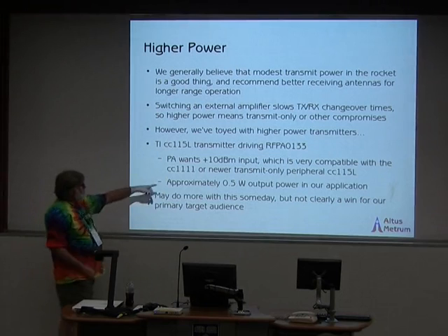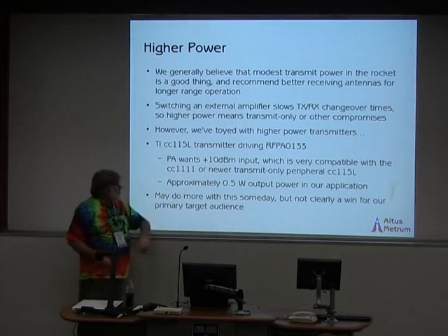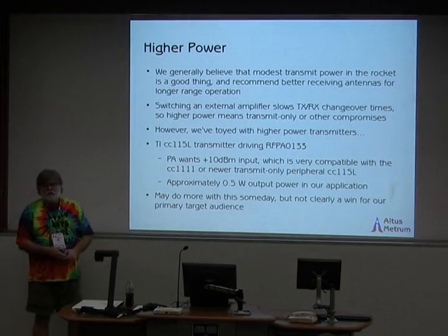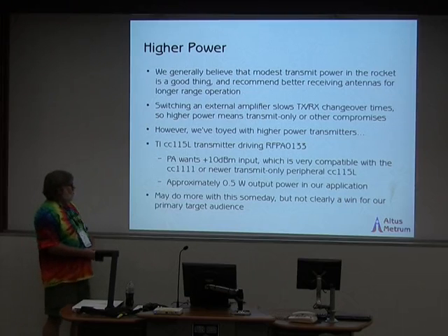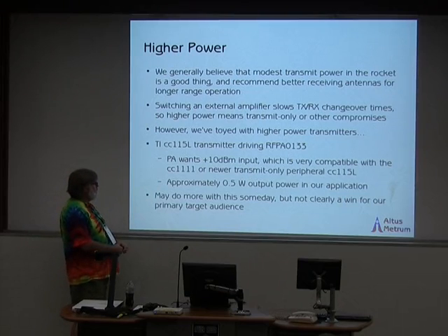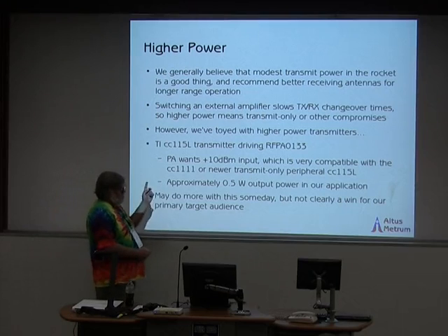And it wants plus 10 dBm as its input, so it's very compatible with either the CC1111 or the CC115L, which can be programmed to put out sort of whatever power level you want.